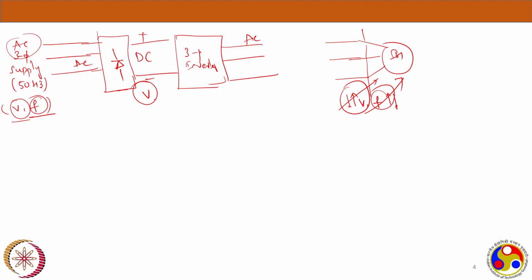So the way with which you switch on and off the transistor switches, IGBTs, anything, whatever you are using within the inverter, if you are able to control the voltage and frequency of the output signal, it's always very good, because you are able to achieve this concept of having variable voltage as well as frequency, right?